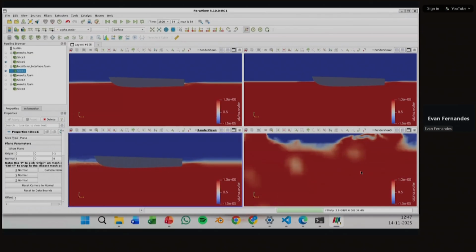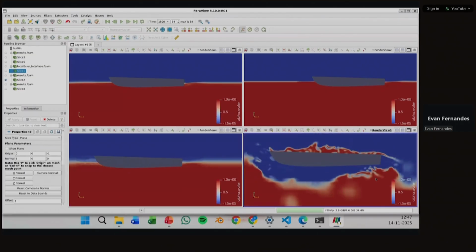And then we have this one. It's a bit distorted, so we can't really see that much. So the Eulerian one, if you compare just the Eulerian and the Crank-Nicholson, you see the difference between the order. As I said, the very first one is first order, this one is second order, and this one is also based on the Eulerian, both of these, but we are changing some of the, like it has the local time step capability. So this one is a bit smeared compared to the Crank Nicholson. The Crank Nicholson is much more refined.